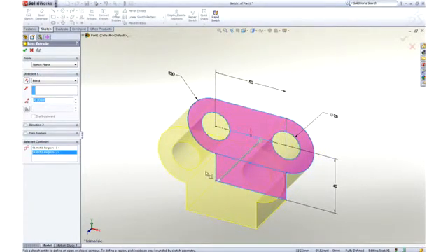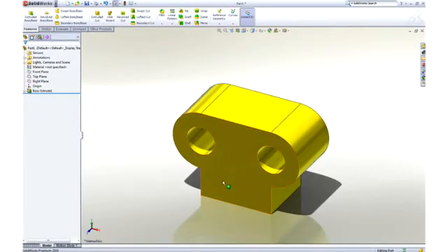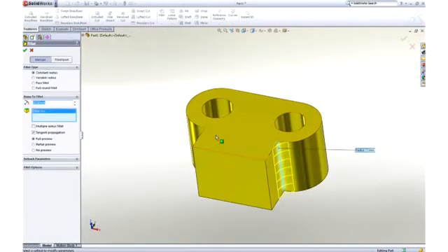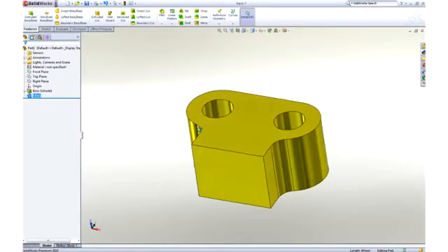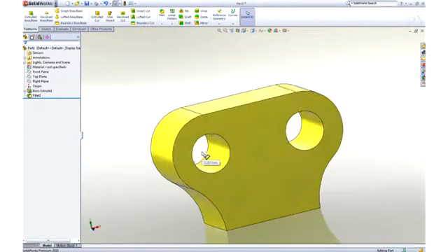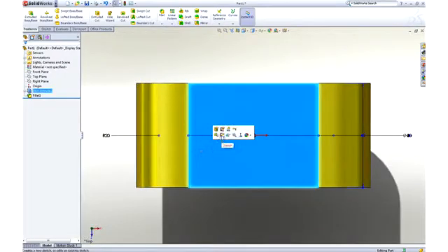It can be extruded in either direction, or in this case we will extrude it 40 millimeters, about the midplane. To smooth some of the sharp corners, we can add some fillets. Their size can be graphically manipulated on screen, or we can key in a dimension to add some precision. Let's add a pocket to the center of the part to accept some links.